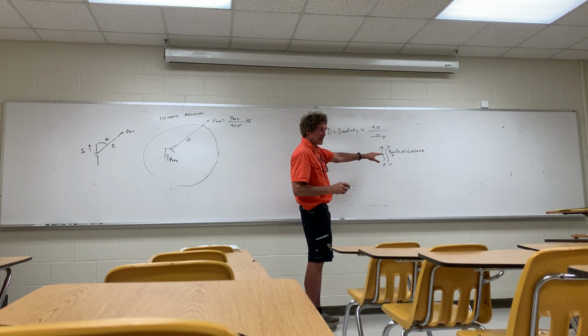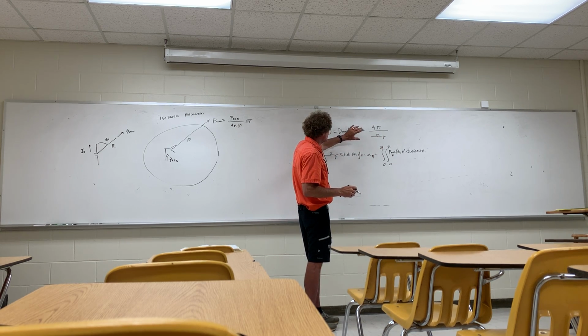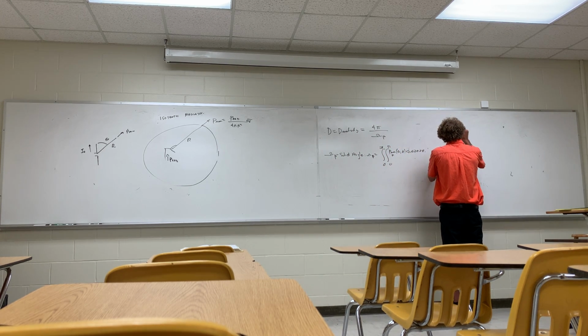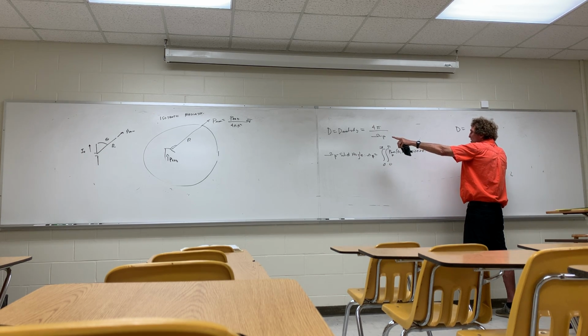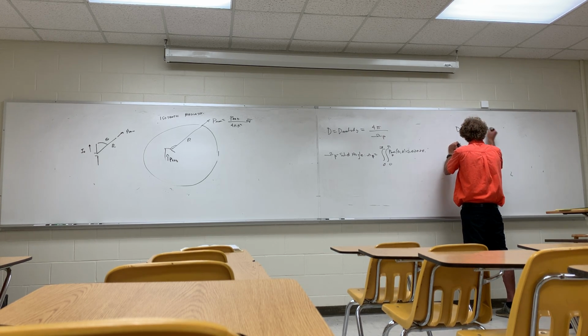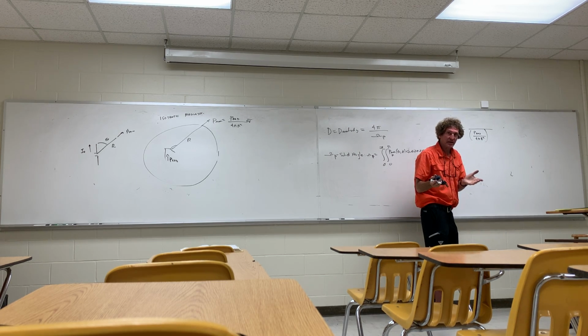Now, I'm gonna do some examples of this. Don't let this bother you. All right. But where this really comes from is if you take directivity in the fundamental definition, well, the average power density, if you think about it, I mean, I'm trying to say this in a way. Normally what you would end up doing is downstairs would be P rad, total power radiated, over 4 pi r squared. That would be the average power density for an isotropic radiator.